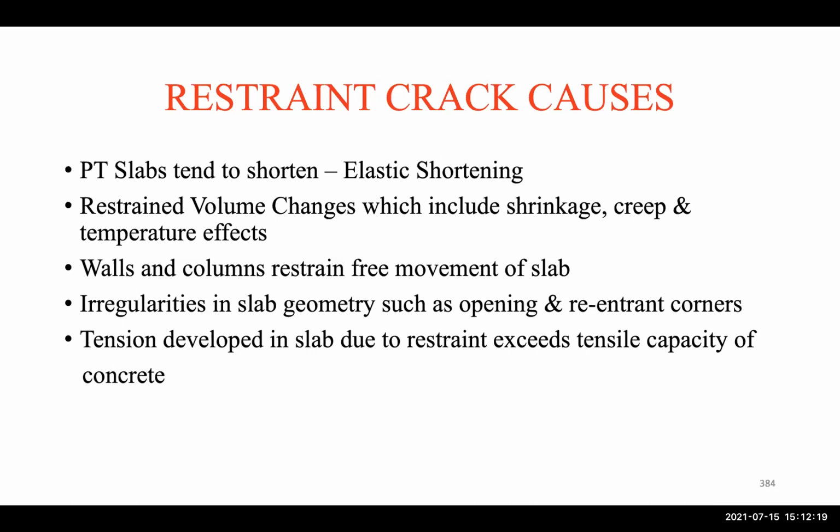Irregularities in slab geometry, such as openings or re-entrant corners. So if there's a big opening, like for the stairs, for the elevator, or if it's a gallery, then these are openings within the floor. So how we detail around the openings is important. The slab tends to move, so these corners will have high stress concentration, and then they will result in cracks, of course.